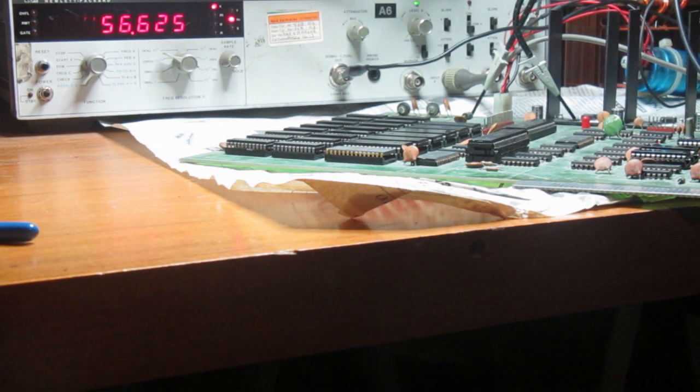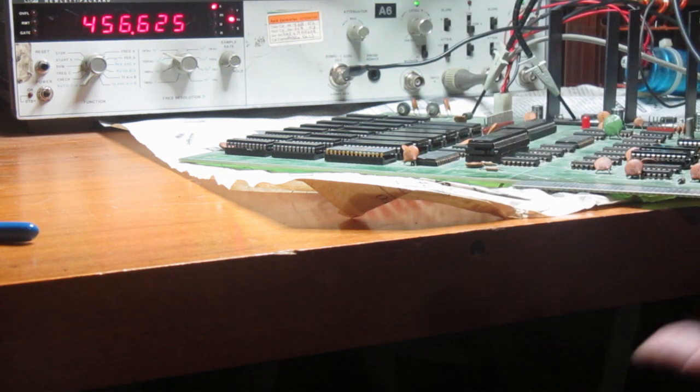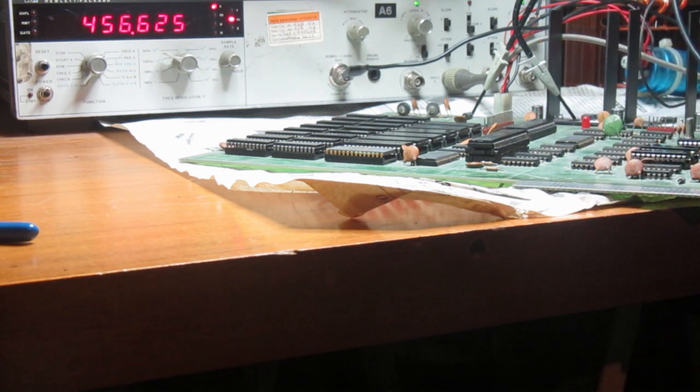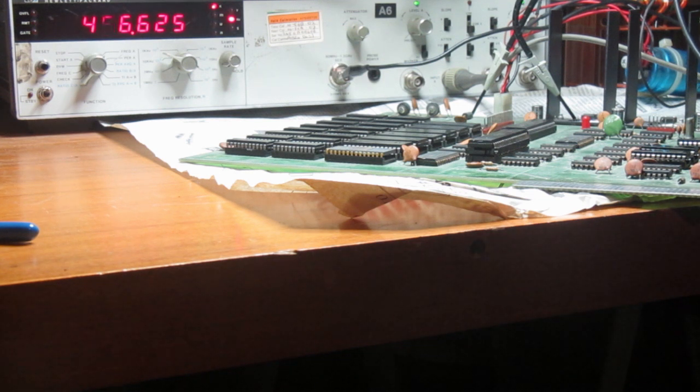Okay, so this is the demonstration setup for the 6502 NOP generator, and I'm using my PET 2001 motherboard that I still didn't install in the original case, but hope shortly to do that. Anyway, as we said, the NOP generator should be used after checking the basic working of the power supply and clock generation.